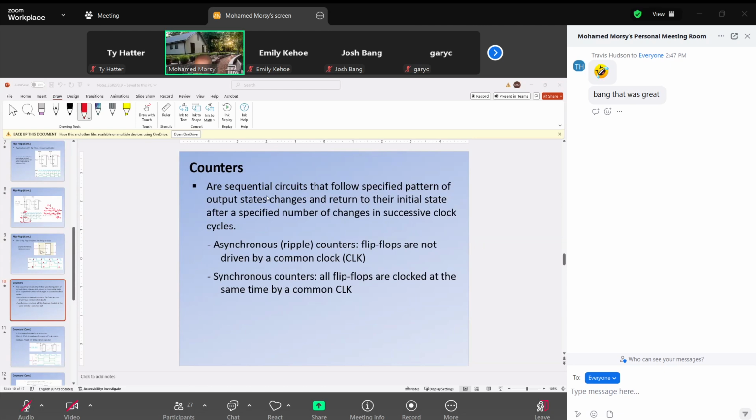Thank you. We mentioned that in sequential circuits we have clock pulses. In combinational circuits, we don't have clock pulses. So the output in combinational circuits depends on the inputs only, but in a sequential circuit it depends on the inputs and the clock pulse. We mentioned the changes happen with the clock pulses. But if you go back to the multiplexer, comparator, or subtractor, there are no clock pulses.